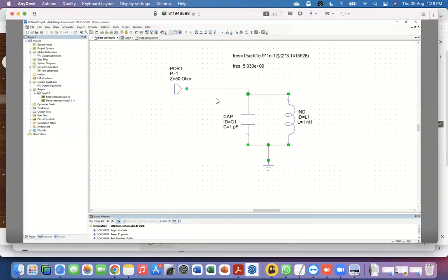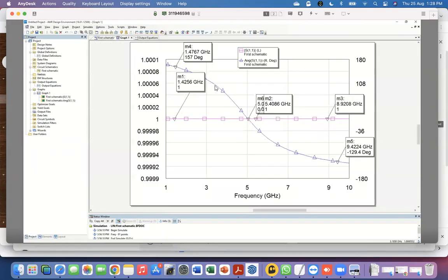So it has no information in the magnitude of the reflection. The information is all contained in the phase of the reflection. And it just so happens that the phase of the reflection goes to 0 exactly at the resonant frequency. This you can calculate once you know the formula for the reflection coefficient, which I'll mention in a second. And that's how you know the resonance.